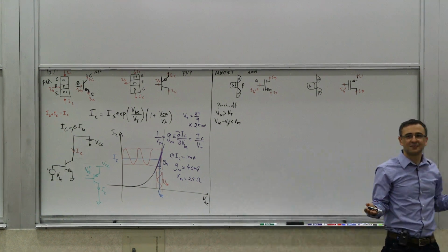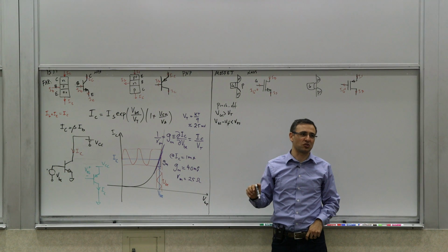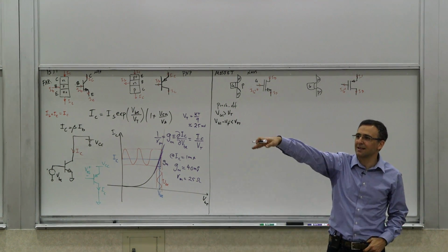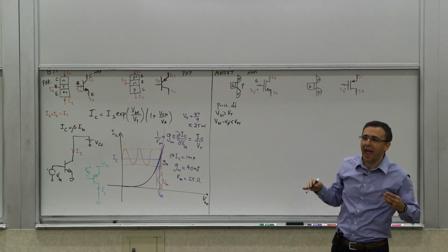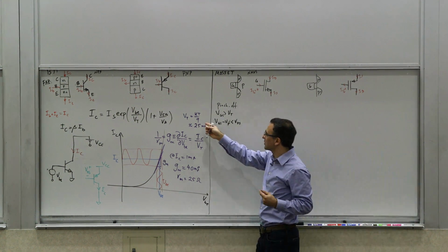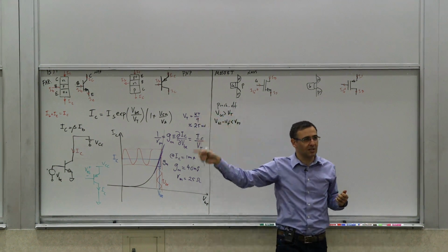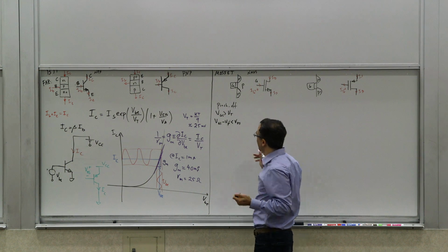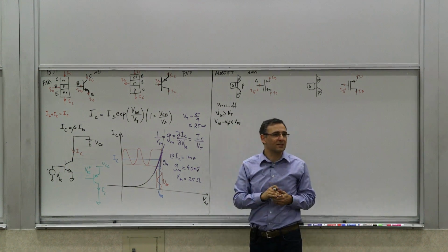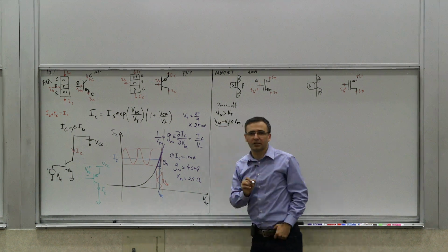So we just know if you're talking about a MOSFET, VT means the threshold voltage that's adjusted by the implant charge and the flat band energy, the differences of the work functions, things of that sort. And if you're talking about a bipolar, we are talking about something related to fundamental constants and temperature: Boltzmann's constant, electronic charge, and the absolute temperature. We can try to avoid this, but now there's a parameter that you can see is a recurring parameter.